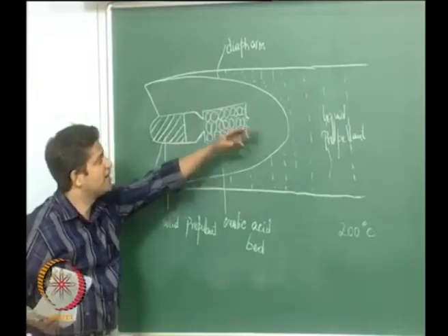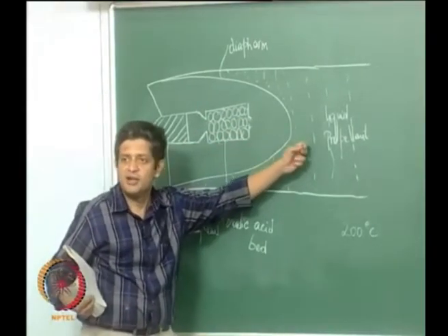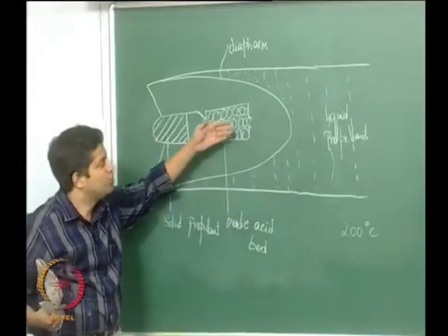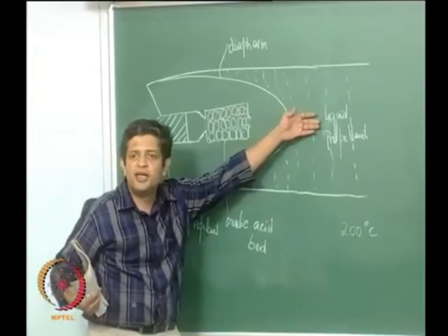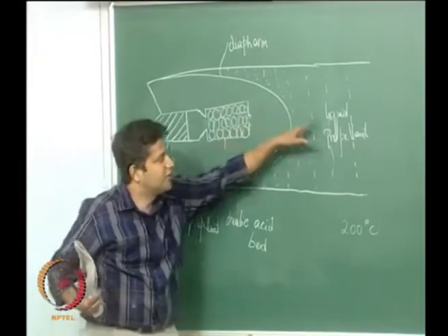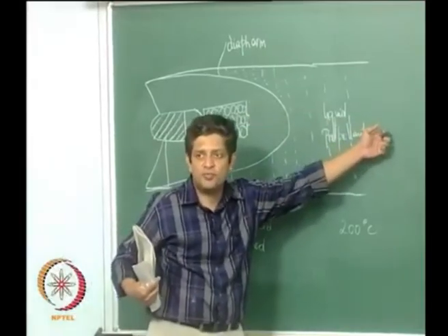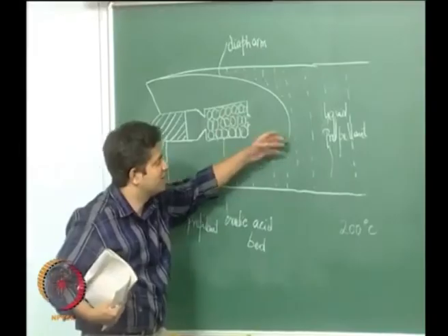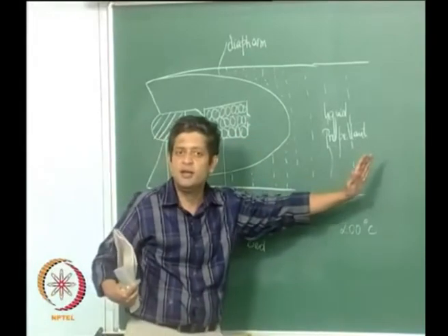So, if you have a diaphragm, you could reduce the temperature across the diaphragm, and also you do not want the pressurizing gases to be interacting directly with the liquid, because then it could directly short circuit and go out of the tank also, right. Then if it pressurizes on this side of the diaphragm, then this can expel out the liquid.